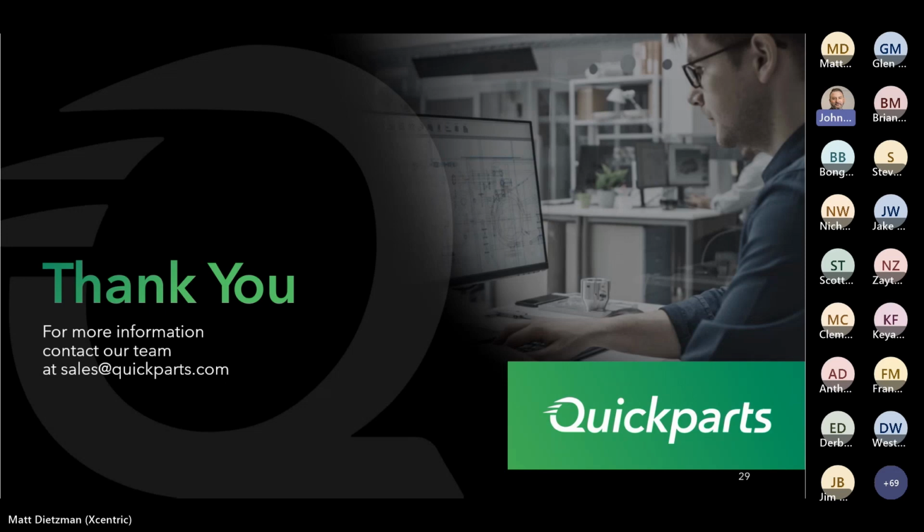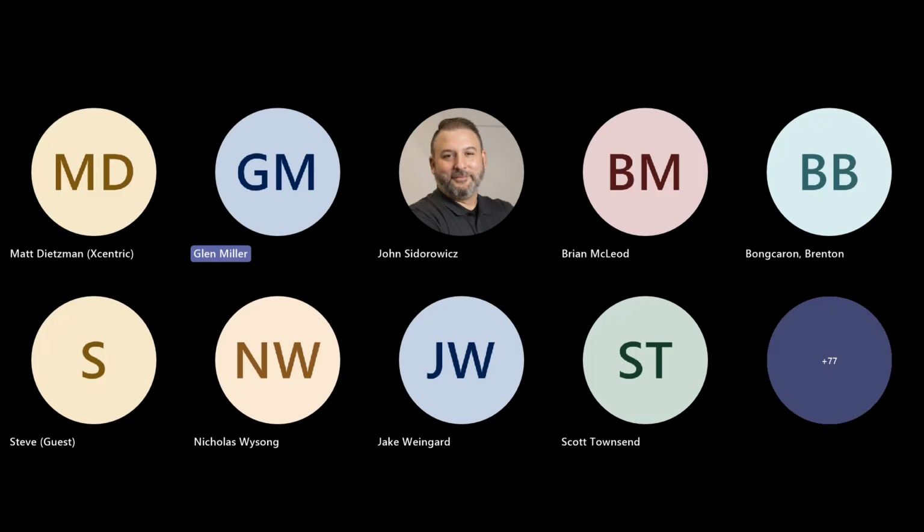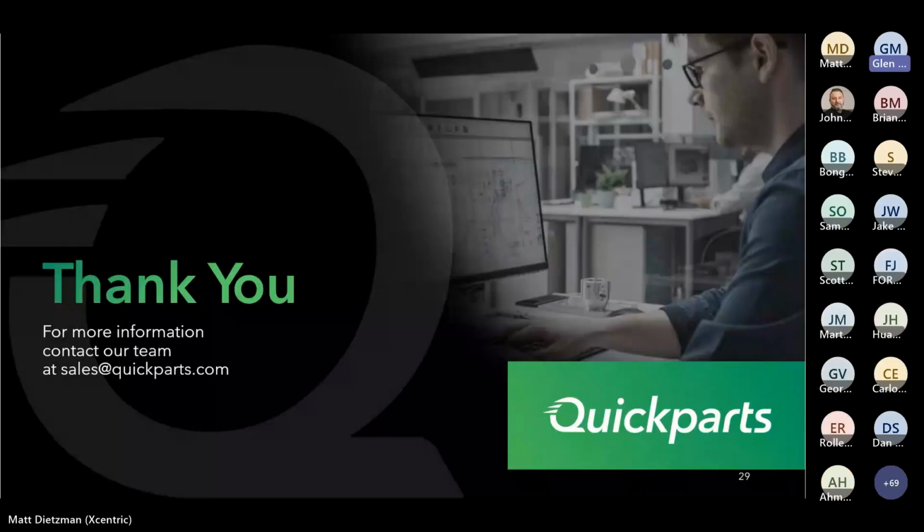Next up, question for the team: could different surface finishes allow material to flow differently and therefore affect the knit lines? Yeah, it definitely can. Absolutely. A high polish, obviously, and it really depends on the material too. There are no hard and fast rules for everything, but there are times when you have some sort of grain on your part, the material will flow a little differently. Nothing too extreme, but it will tend to affect it a little bit.